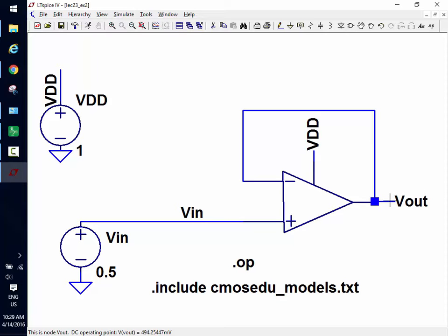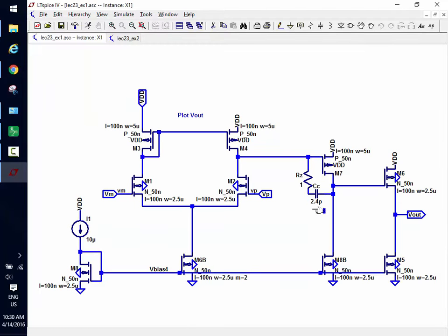And could we calculate based upon the open loop gain what the value of the op-amp open loop gain is? And if the op-amp open loop gain gets higher, what happens? It's closer to. Yeah, so how would I quickly, because I'm learning, and I've got the power of the simulator, how would I quickly increase the op-amp gain?